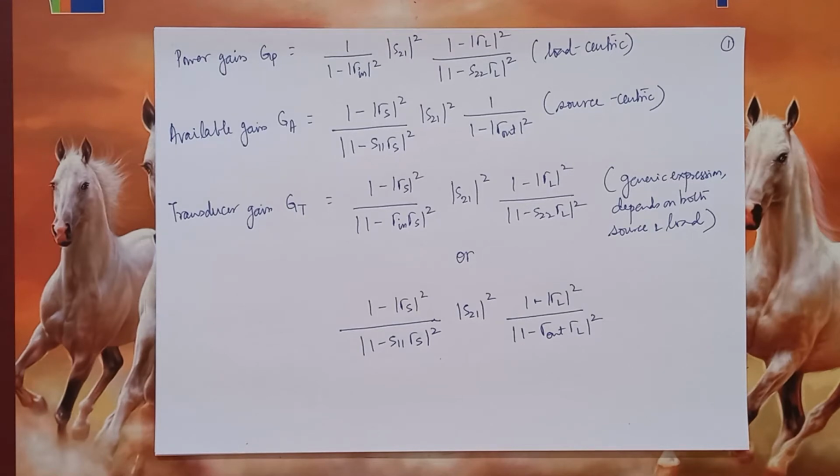So when I'm talking of bounded input and bounded output, the question of stability arises. Whether the amplifier can get us into some trouble and give some voltage output which is much more than its input. Now, when I say output, I don't always mean at port 2. It could also happen that if the input is coming at port 1, the reflected voltage at the same port could be more than that of the input voltage. Well, usually that's not possible because we know that the magnitude of the reflection coefficient is usually below 1. But then again, those definitions were for passive circuits, where there is no possibility of having any gamma whose magnitude could be more than 1.